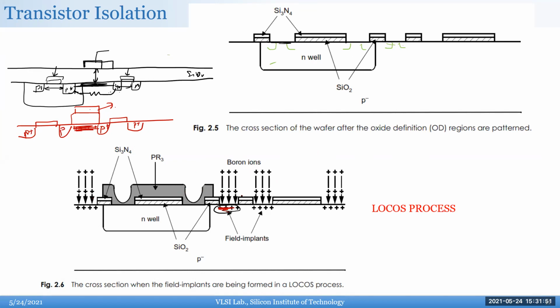That's the whole idea. And this is a good place for using a negative mask. This is where they do the boron implant, wherever there is no diffusion. For example, in order to make a transistor, you usually do a diffusion and you draw a gate length here, right? These implants they do wherever there is no diffusion. So they'll do a negative mask of diffusion.